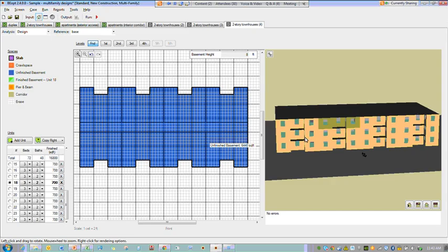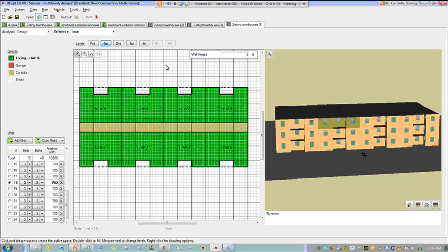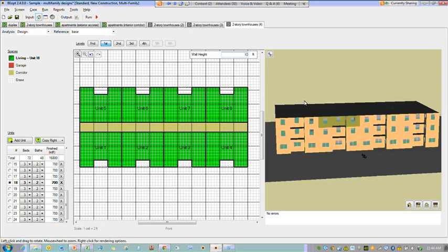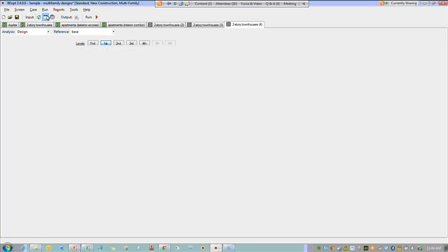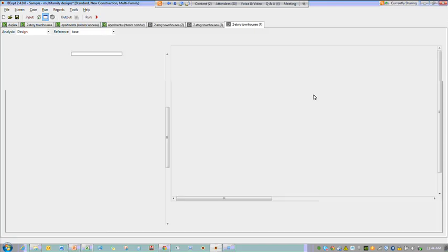And I know that conditioned plenum space can be common in multifamily buildings and a common location for ductwork. And the way we recommend modeling that is increasing the wall height. So say your floor to ceiling height is 8 feet, but your floor to floor height is 10 feet. You could change that wall height to 10 feet to account for a 2-foot conditioned plenum. And similar to the equipment sizing, if you specify user specified duct location, then that's going to be applied to all units.